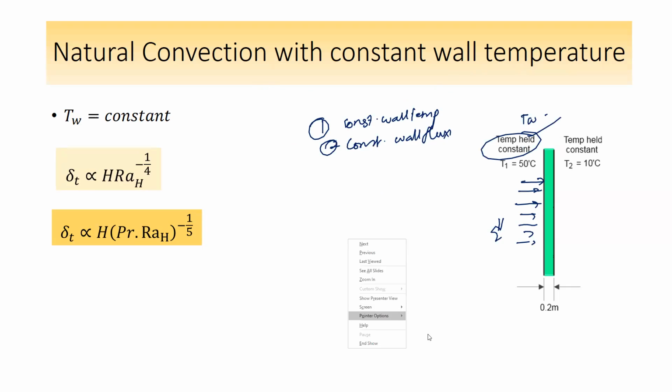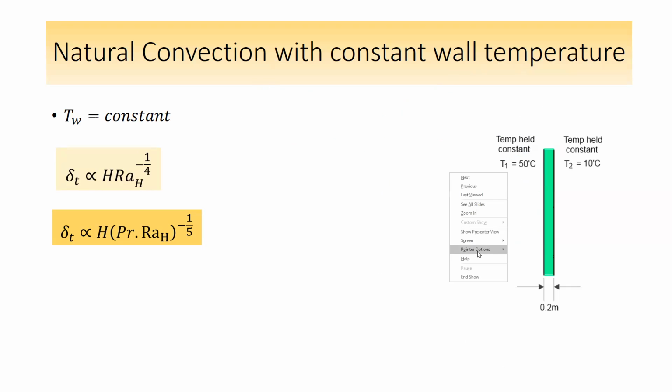Okay. So how does the temperature remain the same? Suppose if the temperature is to be constant, what should happen? Whatever heat is supplied should be equal to the heat leaving, as done in our problems. So steady state condition. Whatever heat comes in is the heat leaving. There is no internal heat generation happening. Okay, that's the condition. Then we are keeping the temperature held constant.